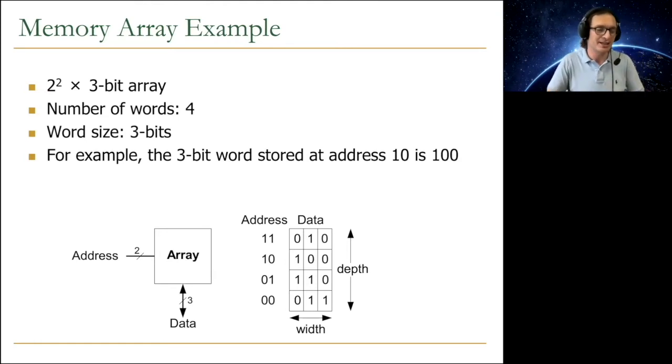Of course, today's DRAM technologies are more complicated than that, but this is a good first order approximation. If you have a more or less rectangular array, 16,000 rows and 8 kilobytes row size, then you pack enough bits over there so that you maximize the bits per millimeter square, let's say. That's how array size is usually determined.